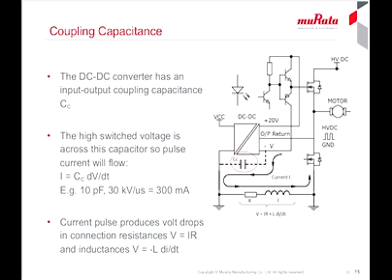This current finds a return path to the switch through the system earthing and will cause voltage drops across resistances and inductances. The voltages add to EMI and can cause interference or even malfunction of the control electronics.